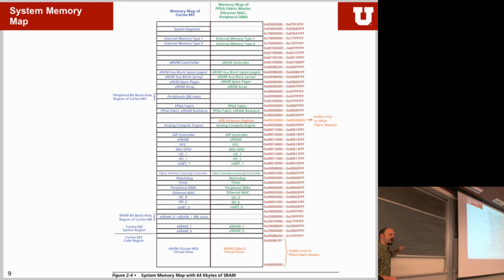If you write into it, you will change the status of that I/O line. So how do you make sure that you only change, for example, bit number 30 without having to go and change any of the other bits? You can create a mask, yes.